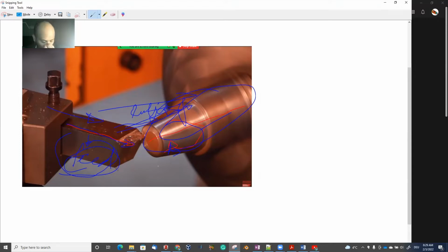It actually decides the movement of the workpiece, and the feed rate and depth of cut will decide how far you should move toward the object. The feed rate is how much material you have to remove per second. Then you could also calculate a material removal rate.